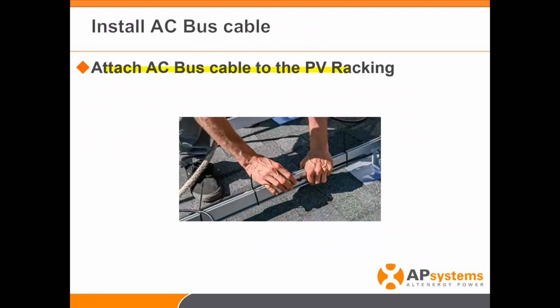Wire management. You can use cable ties, cable clips, whatever you choose, whatever your jurisdiction requires. We don't have a preference on one or the other. I'm a bigger fan of the larger plastic clips or metal clips, just because this is going to be sitting on a roof for 25 years or more. I want to make sure that the longevity is there and you have good wire management, and wires not sitting on the roof a year later.